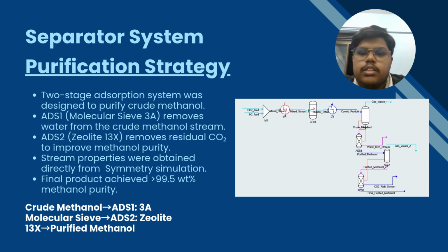All right then. So now it is for purification strategy. So to purify the crude methanol, we designed a two-stage adsorption system. First, the crude methanol enters the ADS1, which contains molecular sieve 3A. The main purpose of this column is to remove water from the crude methanol stream.